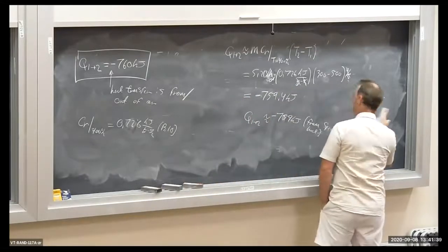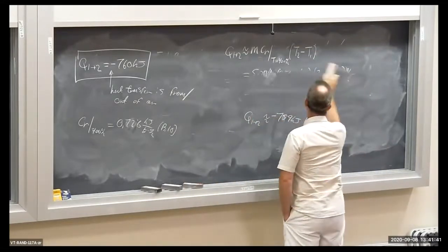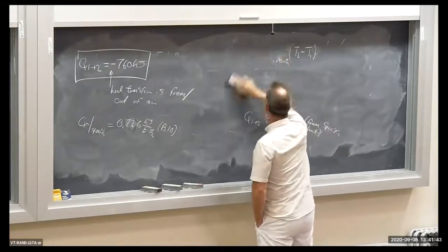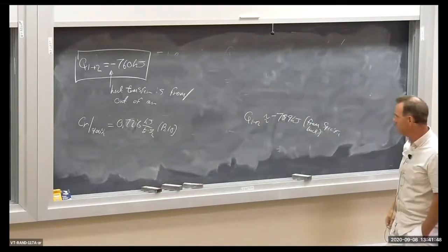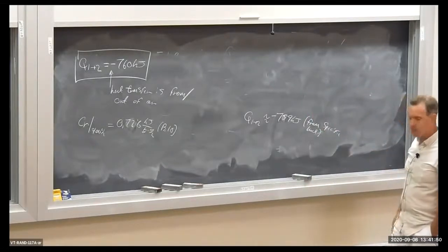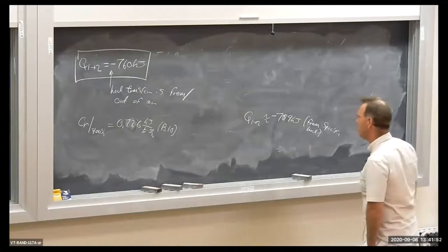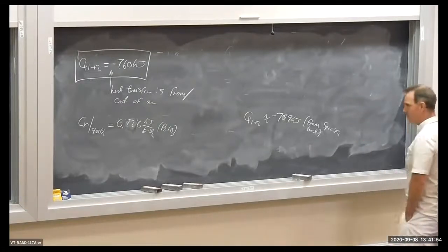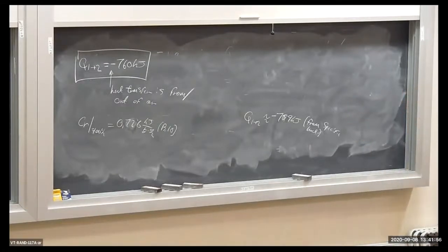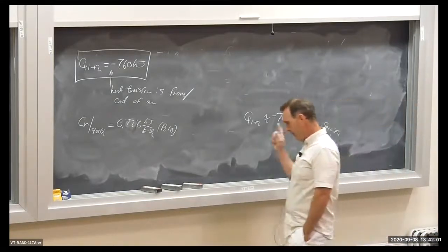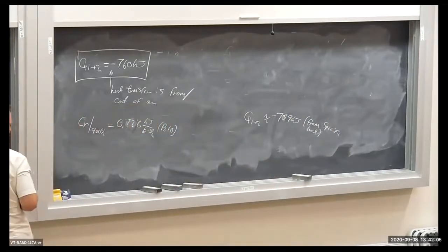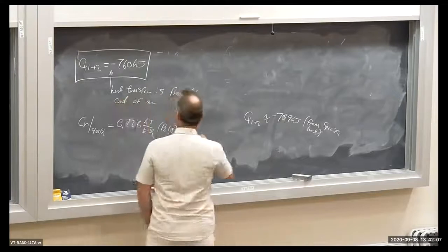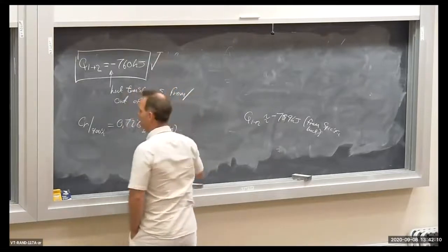Good idea when you do a calculation to be able to get it from different means, okay? So let's get this cleaned up. The actual heat transfer is 760 kilojoules out of the system. And from constant specific heats, we verified that using the definition of specific heat, constant volume, it's an isochoric process, and we get 759 kilojoules, very close to 760, okay? Good check. So I'm going to put a check right here, that looks good.